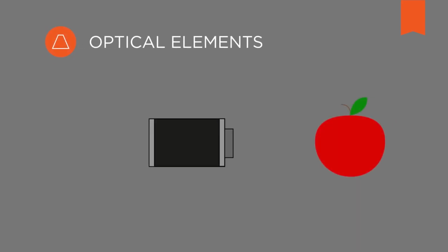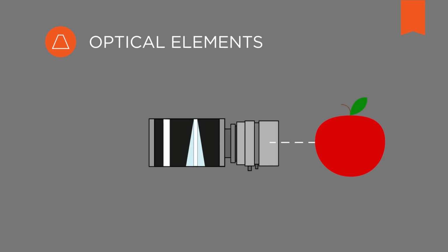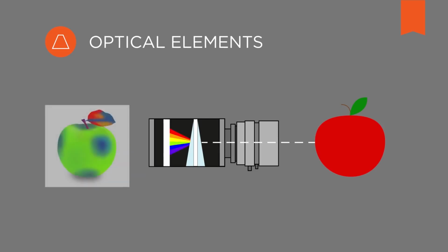Multispectral cameras with optical elements consist of a prism, a sensor, gratings and lenses. The light enters the camera through a slit. The prism and gratings refract the light. The line scan sensor can then generate a multispectral image, line by line. One disadvantage of this scanning type is that the performance strongly depends on the alignment of the optical elements. Calibration is crucial and can be very costly.